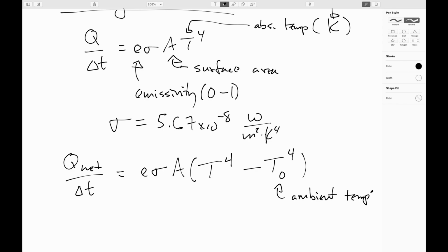And of course, what really matters here is the emissivity in the infrared. A lot of materials you can just quote one number for, but sometimes you gotta be a little fussier. But in any event, a dark t-shirt will do a better job of both radiating and absorbing heat. But if the ambient temperature is really close to your body temperature, then that could actually be a bit of a problem.